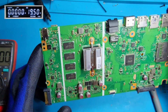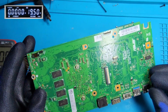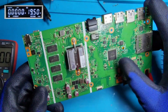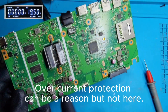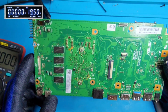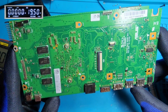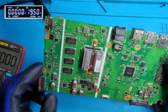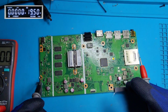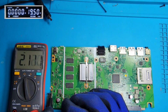So the charger IC is actually cutting the voltage into the motherboard. If the charger IC senses that a high current is being drawn by the components in the motherboard, then it will cut the voltage into the motherboard here. There can be this instance. So we need to check why it is switching the main power rail on and off, because we don't have any short. So okay, let me check the inductors.